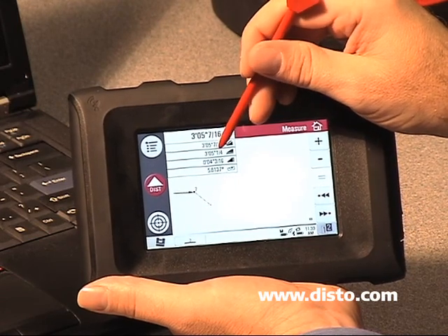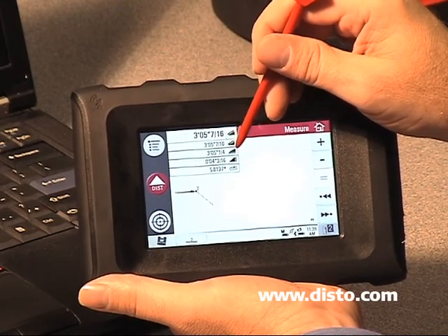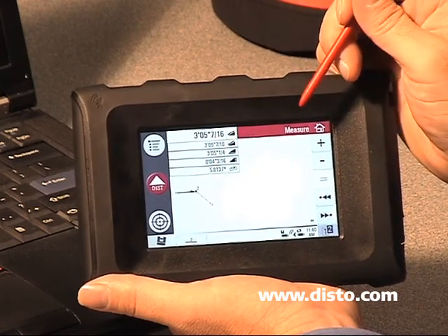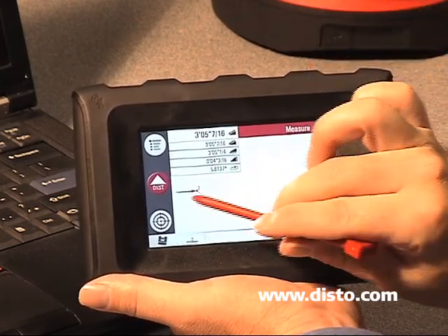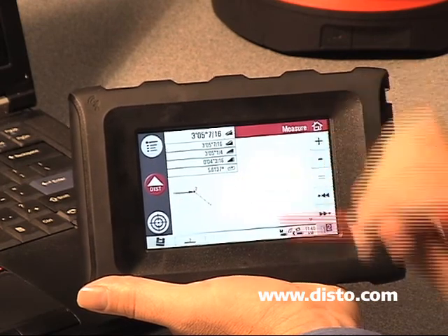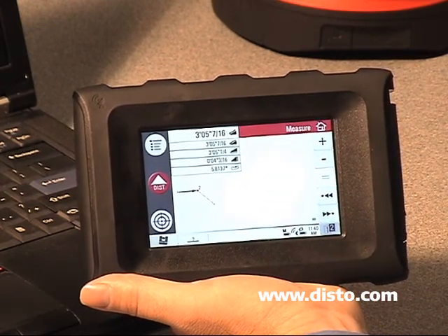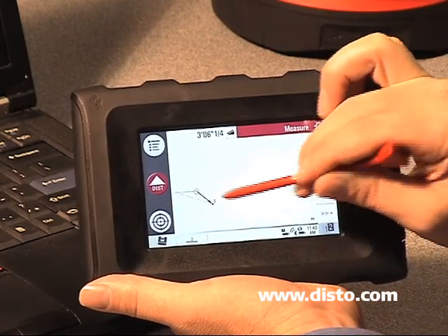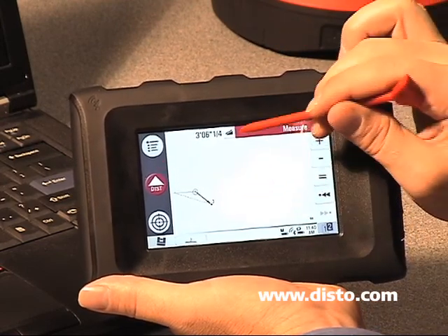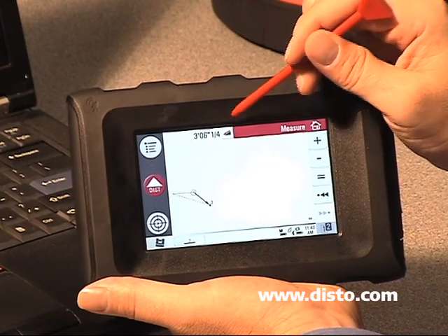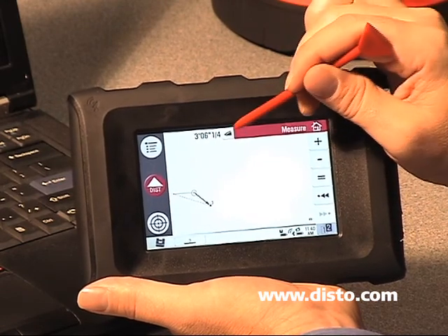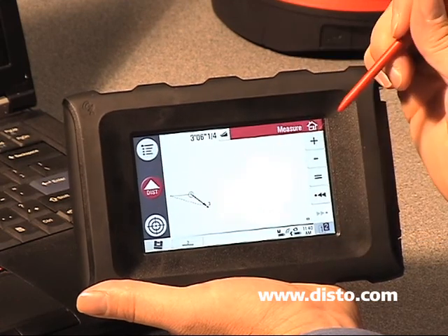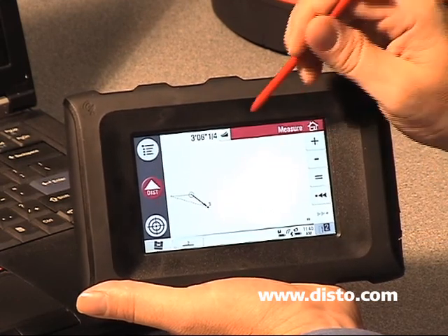The horizontal change in distance was 3 feet 5 and 1/4. The change in elevation was 4 inches and 3/16, and that line segment from line 1 to line 2 was a 5.1837 degree slope. If I click on the second line segment, we've got a little bit more information. Again, we've got our 3, 6 and 1/4, but also note that there are 2 half circles around that corner, around that intersection of those 2 lines.